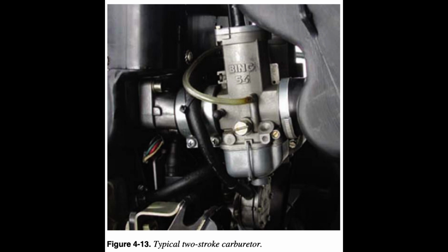The roughness is usually due to spark plug fouling from excessive carbon buildup on the plugs. Carbon buildup occurs because the excessively rich mixture lowers the temperature inside the cylinder, inhibiting complete combustion of the fuel. This condition may occur at high elevation airports and during climbs or cruise flight at high altitudes.